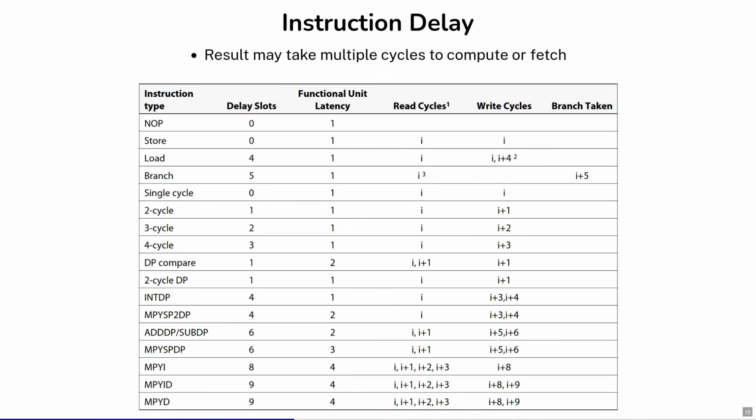One more core feature of this architecture is that every piece of information about how long an instruction executes is provided at compile time. And this is an overview for all the instructions. The important part is first the functional unit latency, which explains if we execute an instruction, how long the functional unit will be blocked. One cycle is the default, meaning we can execute something each cycle, but more complex instructions will block the unit longer.